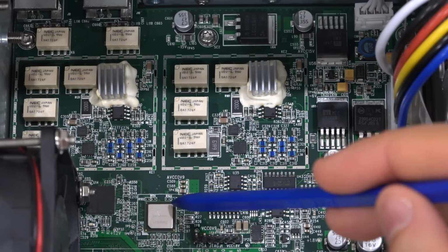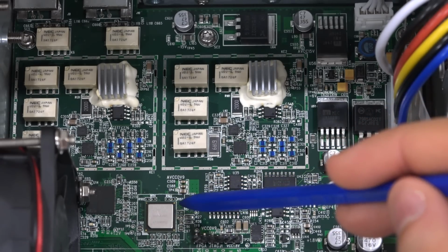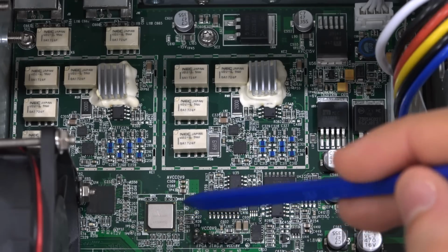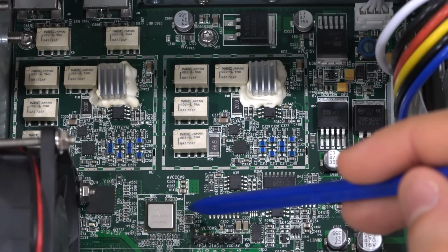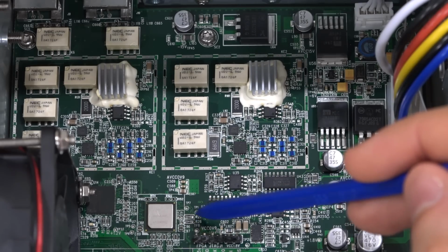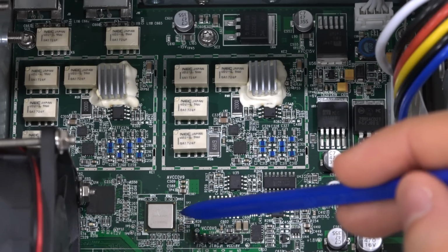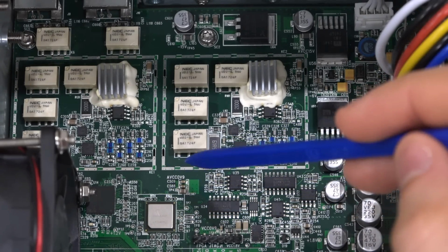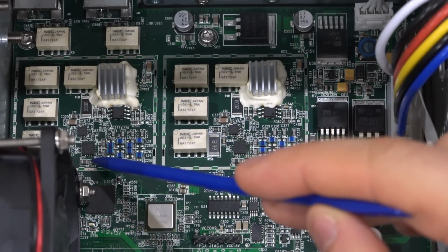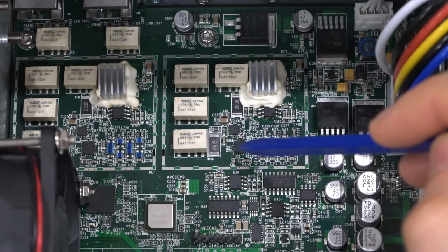Now the differential output is unfortunately not preserved, and this instrument gives you single-ended output, which means that there needs to be some components to do differential to single-ended conversion with some additional gain and gain control and other capabilities. And they have used a Texas Instruments THS3217, and that's this component over here, and there's also this component over here.